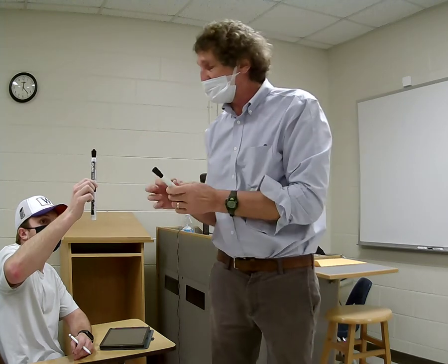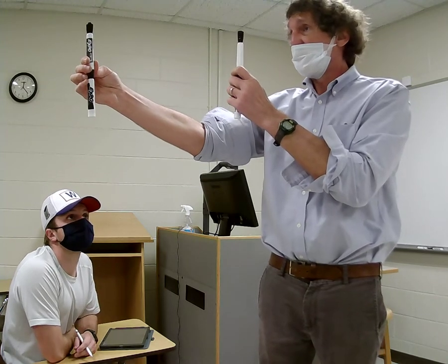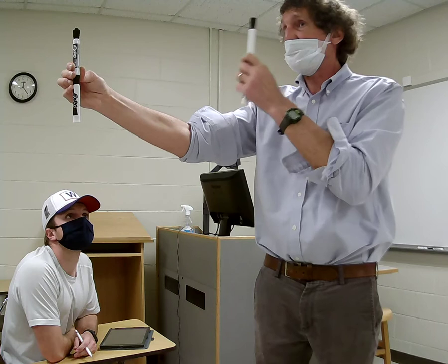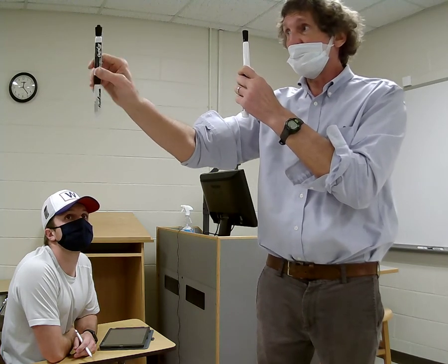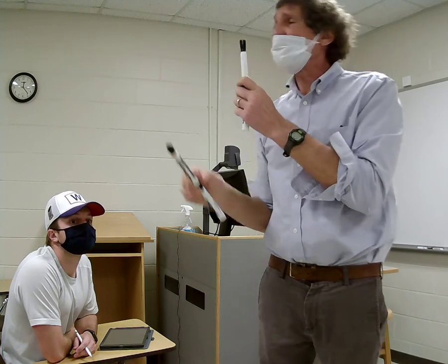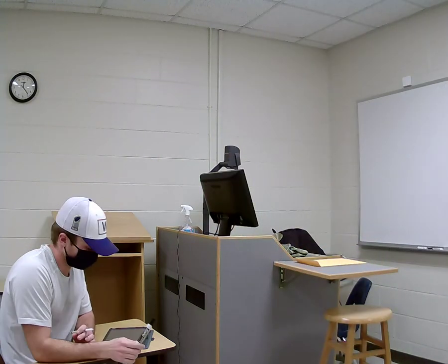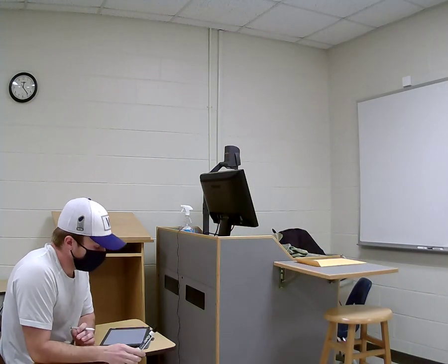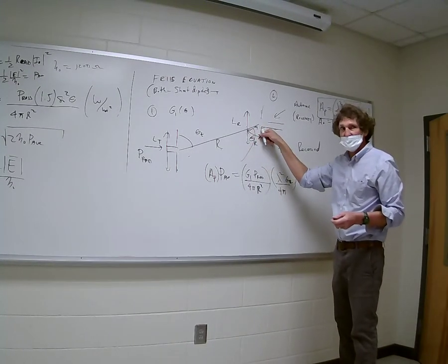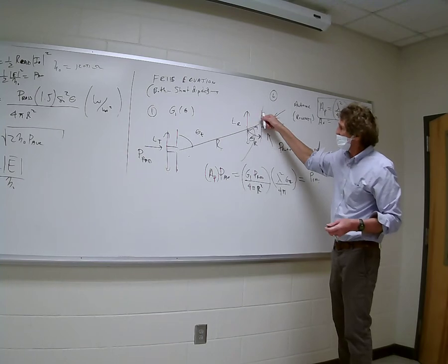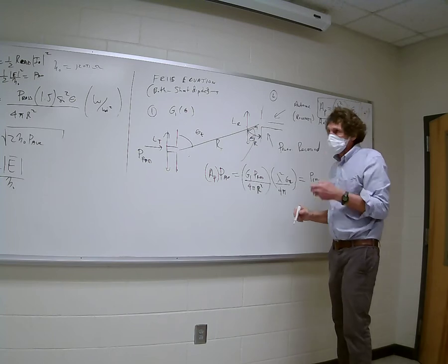Now, I'm trying to get you to see physically in your mind's eye what's going on. This is maximum, right? Now, if I take this antenna or this one, I do this, I get 0 this way, right? Or if I take either of these and do this, I get 0. You all see that? That's called polarization loss. And what you have to do, and I'll give you more info on that, when you look at an antenna problem in general, you don't just take a look at the angular difference between R and this axis. You also want to see what the called tilt angle is on that antenna alignment. Are you with me? And it's going to fall off as the cosine of that angle.